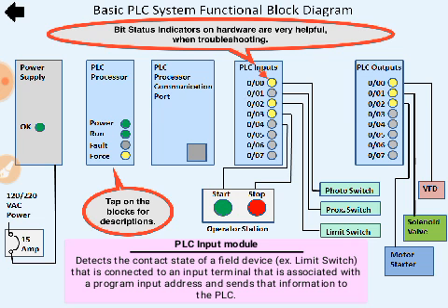Examples are a limit switch and sensors. Another one can be push buttons that are connected to an input terminal that is associated with a program input address and sends that information to the PLC.